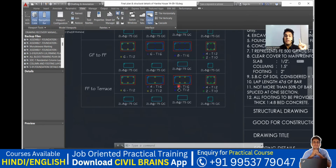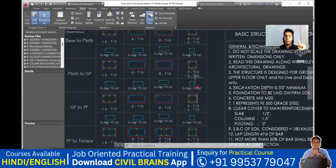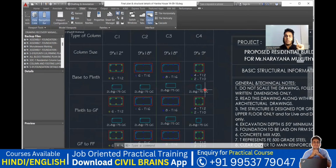4 plus 4 is 8. Here also 8. But the only thing is, instead of 16 diameter 8 number, we are providing 16 diameter 4 and 12 diameter 4. Got it? And same thing here also. Here anyhow, we have kept it very similar.